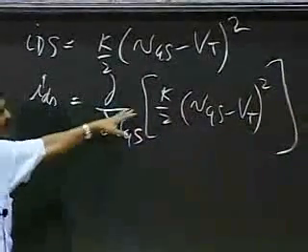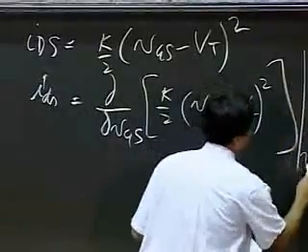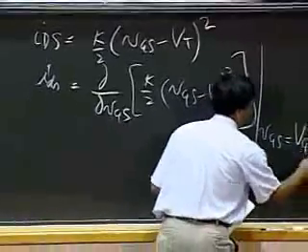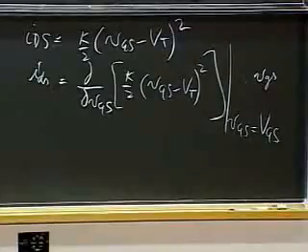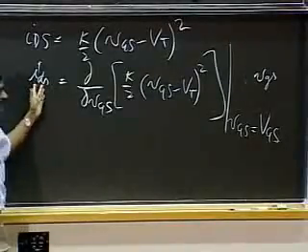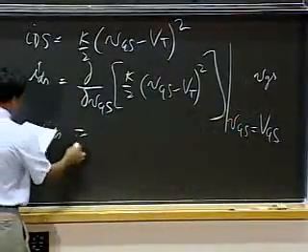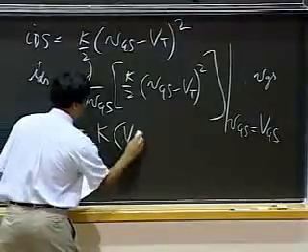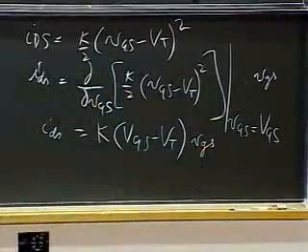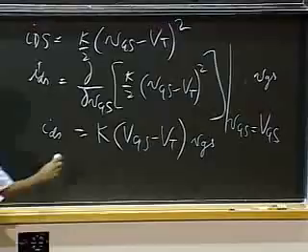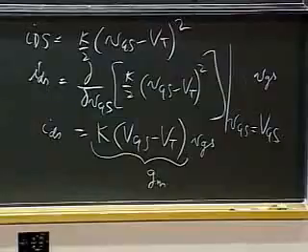So I don't completely eliminate the math here, but it's a much simpler problem. At VGS equals the bias point, times small VGS, I can find the small change in IDS corresponding to a small change in the input using this expression. That gives me IDS is simply K times (VGS minus VT) times small VGS. I call this GM. I'll tell you why in a second.